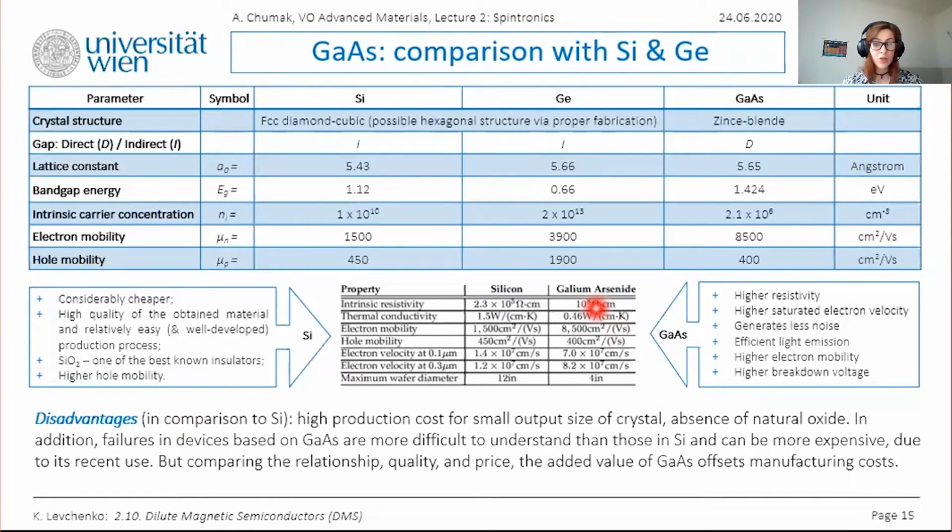current. So in silicon, we have a proportion of electron to hole mobility around 2 to 1, 3 to 1, depending also on the manufacturing process and whether any dopants were used. So it means that P devices have to be twice as wide as N devices in the transistors or in any logic device.